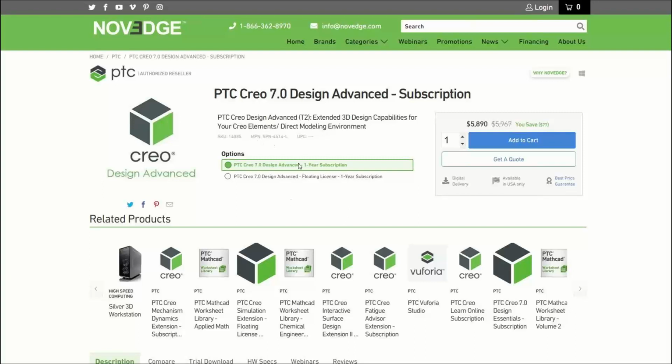Typically what we'll see is people just laying out different configuration files for one of your standard parts that you want to make, and then you could set up a different configuration model specifically for additive manufacturing. And we'll typically do that with lots of different types of manufacturing, whether it be casting or milling. What we'll essentially do is say we're going to make this configuration specifically for the stock piece. And so what that does is if you have changes to the standard file, you can have those all propagated to that specific configuration that you set up for additive manufacturing.